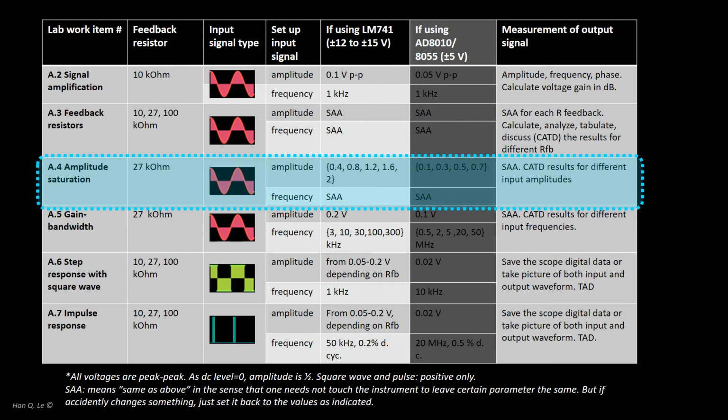If you use 12 volt AC adapters, that will be plus or minus 10.6 volt roughly. If you use 15 volt, it will be around 13.6 volt. Observe the sharp flat top cut off in the output waveforms when saturation effect is dominant, such as with 100 gain, and the output may look like a square wave.